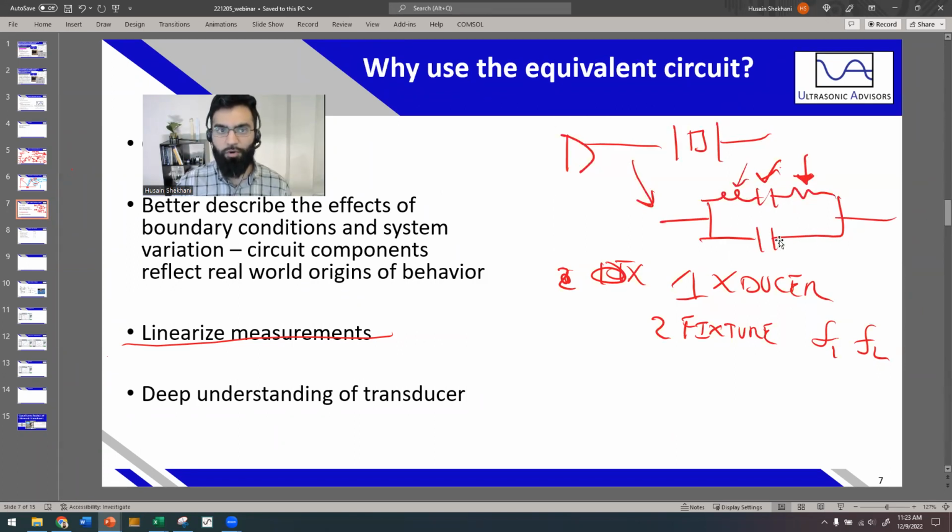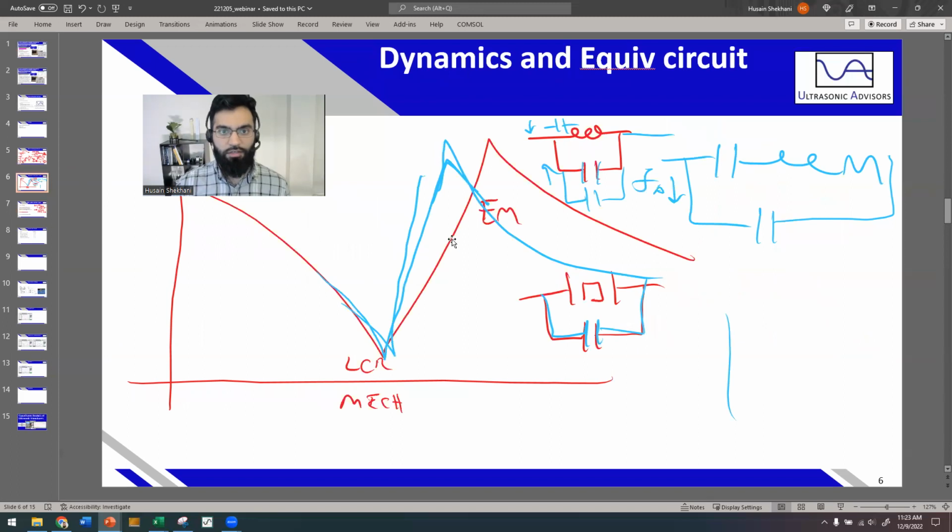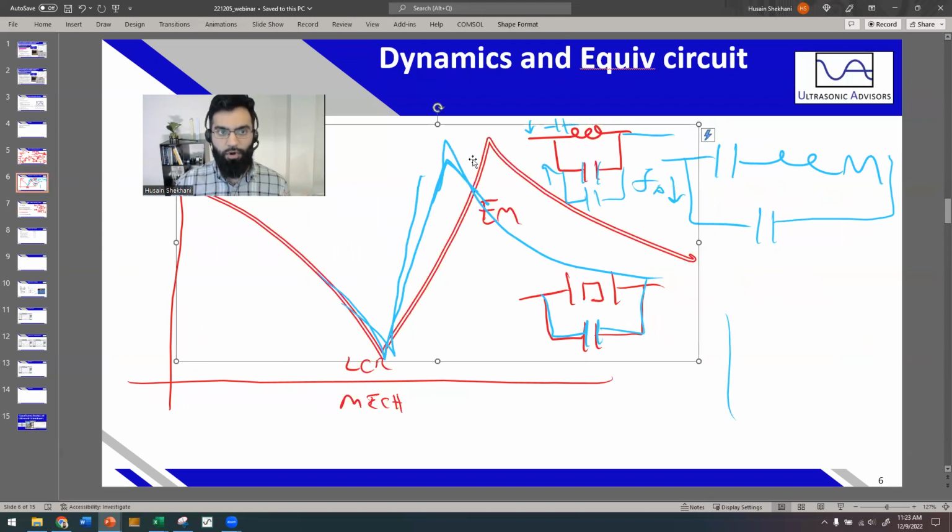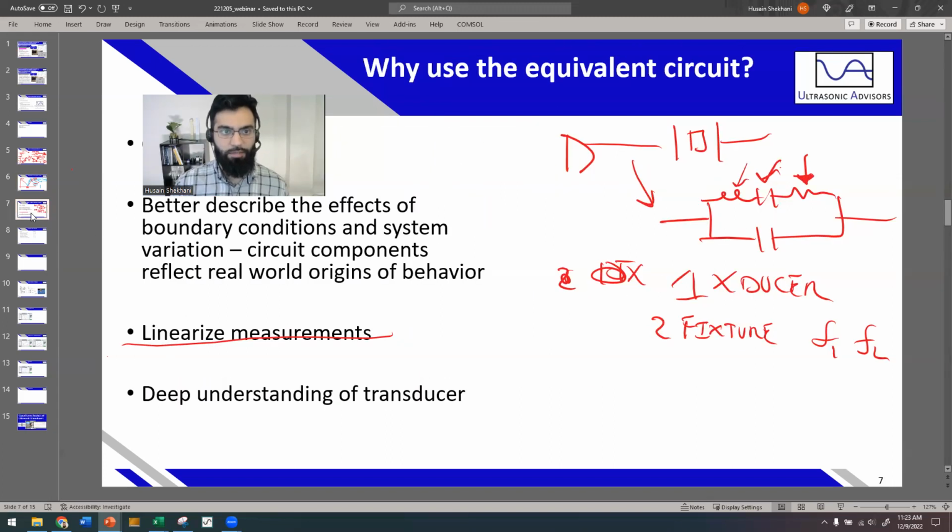These are all linear components. There's nothing nonlinear happening here. It's just based off the linear piezoelectric effect, or an effective piezoelectric effect for your transducer, and there's a resonant frequency, and all of that is good in linear components added to each other. Nothing in this ultrasonic behavior, resonance and anti-resonance, is something beyond normal mathematics of circuits.